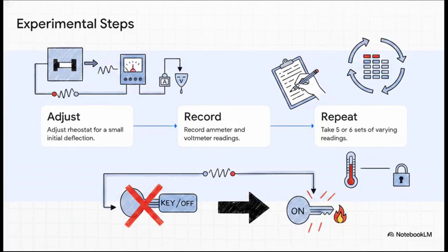Now, remember what we said about Ohm's law and temperature? Here is the absolute most critical part of your lab technique. Only insert the plug key while you are actively taking a reading. If you leave that key plugged in, a large current is just going to keep flowing, it'll overheat your devices and completely ruin the accuracy of your results. Seriously, keep an eye on that key.